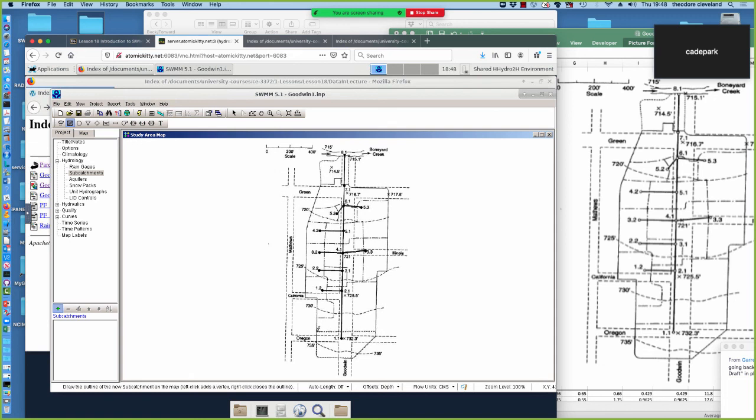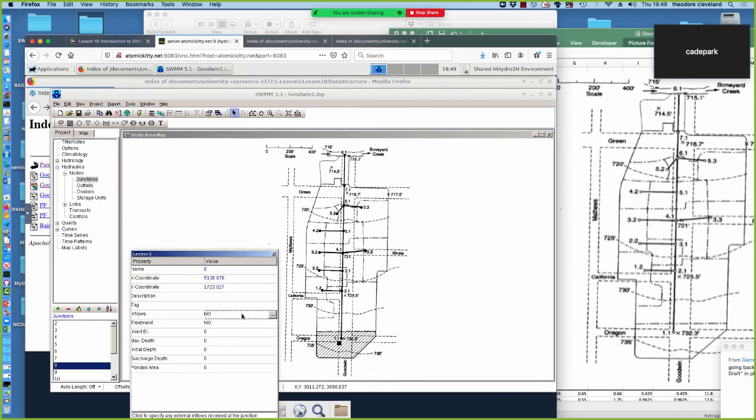It's not doing any sort of area calculation, and it stores it as a shaded area, and then we will have to manually assign the acreage and a few other features to get water to leave that drainage area and enter. In this case, we're going to send it to that first node, which is node 1-1. So we'll set just that up, and then we'll be done for the day.